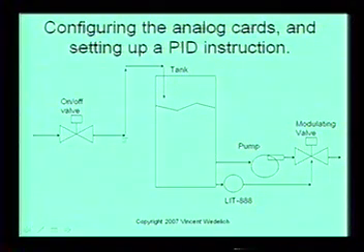Whenever this valve is open, then the tank just fills up, right? And then the idea is to pump the tank empty right here, just to let it out. And if this valve is fully open and this pump is just on all the time, it doesn't have a variable frequency drive on it or anything like that. It's just wide open. A variable frequency drive actually varies the speed of the pump. So you can actually vary the frequency of the pump, and that's another one of those short courses, the VFD course. So the pump is, in this case, just on-off.